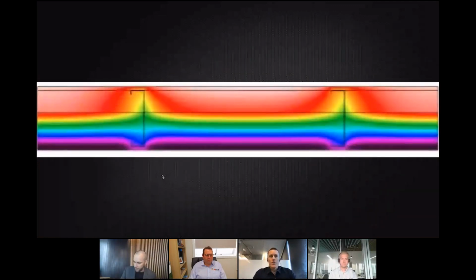And then we jump into the steel frame, which we've seen on screen a couple of times, this time with this thermal modeling showing how the temperatures are actually changing around that steel. So this is what I'd call wild lines of temperature gradients. The heat is being transferred really fast through the steel, as we've already seen, but it's only 1 millimeter of steel. I mean, how bad can it be? Well, we know it's bad. We had it on screen earlier, 1,300 times difference in the heat transfer through that steel.